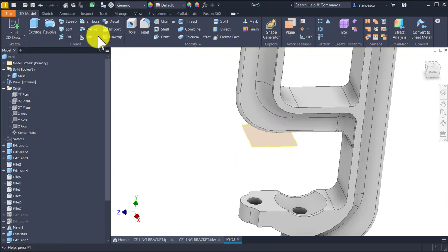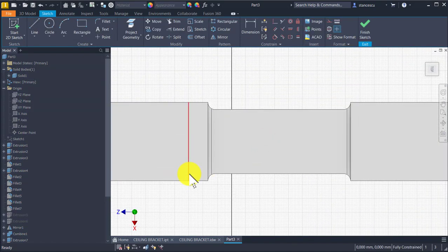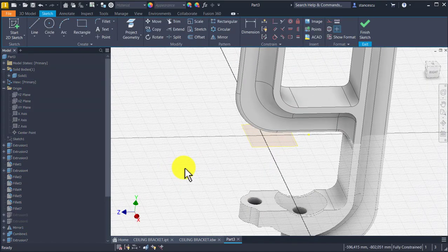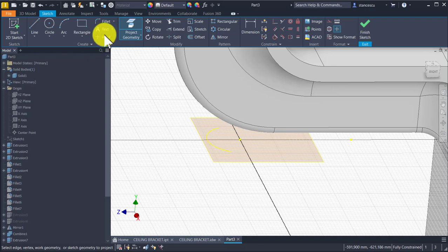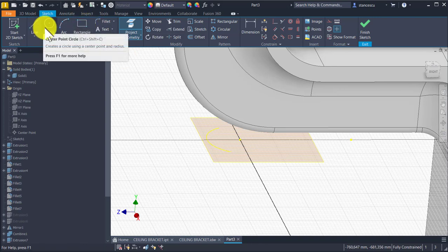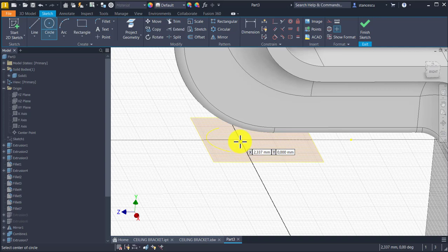We project here, we create a sketch, and we project. F6 to see, no, F5 to see back. I project this circle here. Control Z, not the circle, the arc. I prefer the arc because I don't need to apply construction. 35 is the diameter.